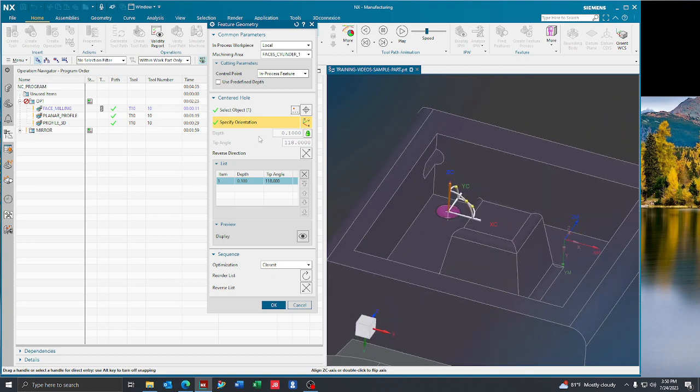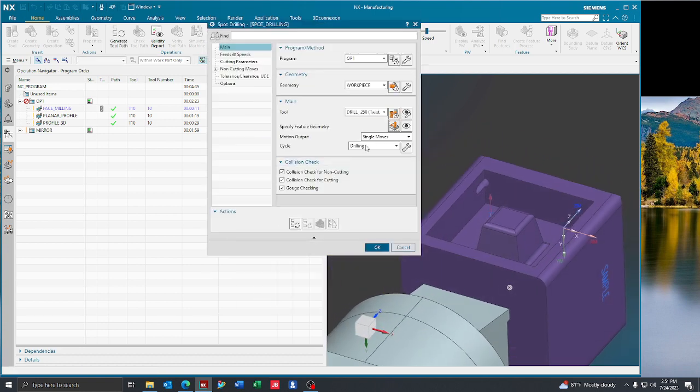That looks good. Now, the reason I moved that point up 100 thousandths is because of the drilling depth. You have to give your drill a depth to go to. Even if it's only 1/10 of an inch, it must have a depth. So I can unlock this for my depth, and I'm going to put 75 thousandths here. That way I am staying 25 thousandths off the floor with my rough start hole drilling toolpath, and I'm as close as I can comfortably be while still roughing the hole in and not being in a finishing state. I'll say OK, and then we'll just leave this alone.